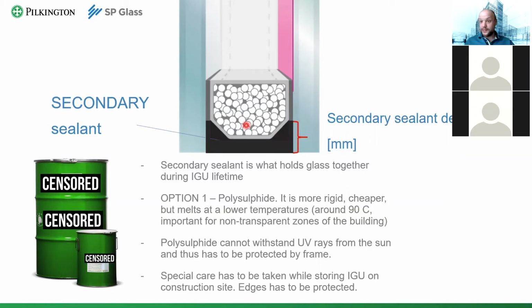So yeah, it holds the glass together. Now, how firmly it holds and how much weight or how much force it can withstand depends on the secondary sealant depth. Basically, the more secondary sealant you apply, the more it can hold.